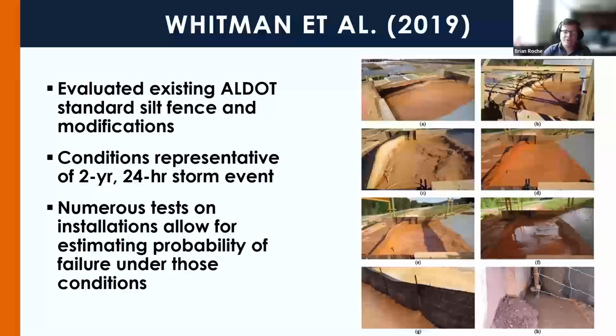The main study we're going to look at was completed here in Auburn a few years ago by Dr. Blake Whitman, who evaluated the existing Alabama DOT standard silt fence under conditions from an average Alabama 2-year 24-hour storm event. And he completed numerous tests that allow us to estimate the probability of failure for these practices, as well as made numerous modifications to the practice.